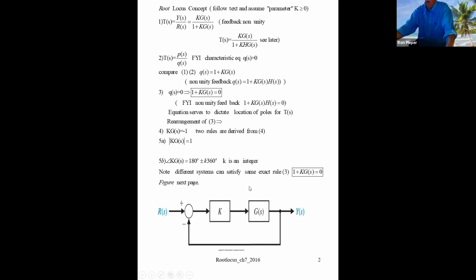However, we can see from the canonical form recipe that this would be the correct canonical form for getting the transfer function. And if I had a transfer function in the feedback loop, it would appear as we see it in the denominator, just so you know. So getting back, in general our transfer functions ultimately will end up as a ratio of polynomials in the numerator and the denominator, consistent with the same notation we used when doing the Routh criteria.